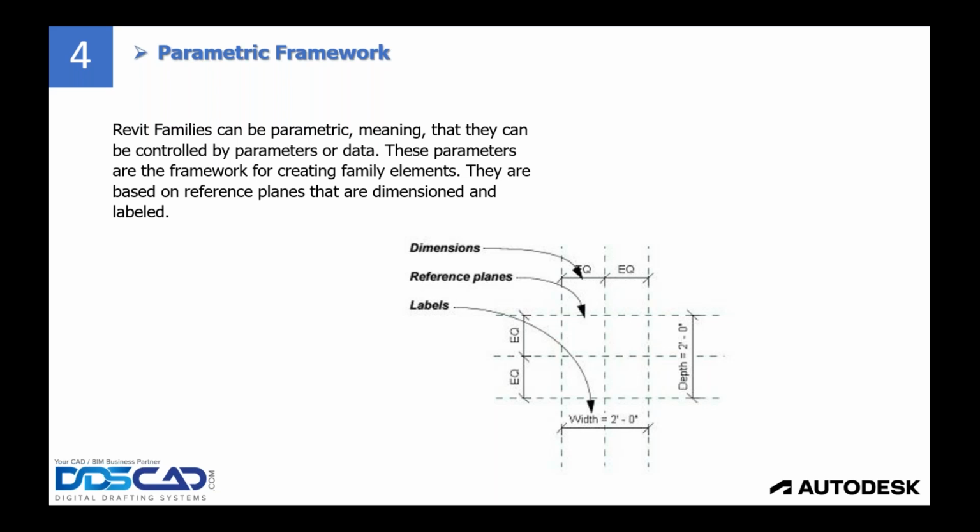The best way to understand that is to see that in Revit we create lines that are green. Sometimes you have seen those lines, which are actually powerful inside Revit, especially in the family editor, and they create those boundaries that we can manipulate. So those reference planes, reference lines, and sometimes even dimensions can constrain some of the elements that we do there.